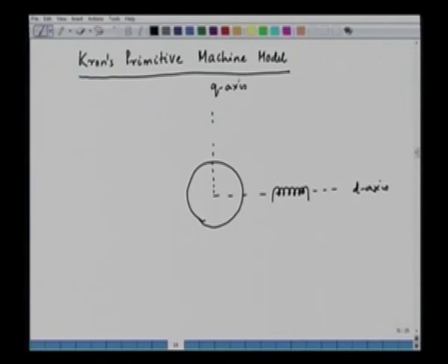We have two different windings, one set of windings in the D axis and the other set of windings in the Q axis. For example, in the D axis we have our winding in the stator. This is the stator winding, which is stationary, not rotating, and this is the rotor, which is rotating in the clockwise direction at the speed of omega r.